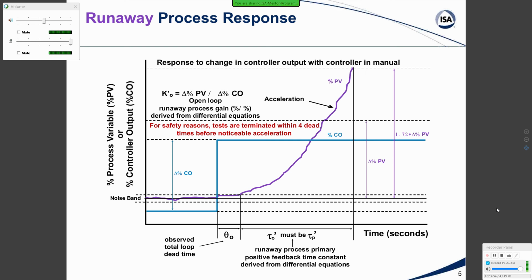It's so important, and you can visualize this: if you have an integrating process and you have a high gain and you make a step change, it'll line out with an offset, but it adds the missing self-regulation. So the proportional gain action adds the negative feedback that's missing in the process. So here we get to the runaway. It becomes even more important that we have this gain action from the PID, and there's actually a window of allowable PID gains.